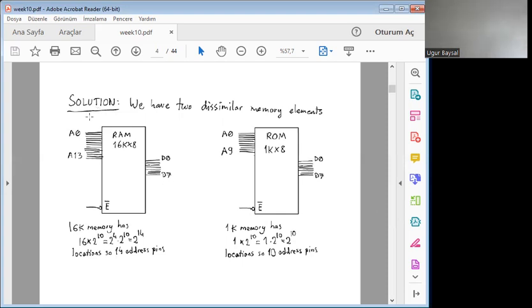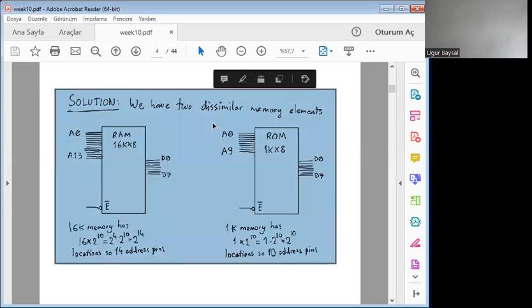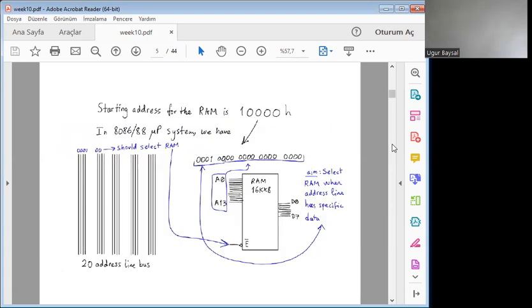As we remember from the lecture notes 2 weeks ago, the RAM has 14 address pins, 8 data bus connections, and 1 enable input. Similarly, from the same week, our ROM consists of 10 address bits and 8 data pins to be connected to the board system, and the reasons for these numbers of pins are given underneath the images. So basically, we are connecting the address bus and data bus coming from the microprocessor.